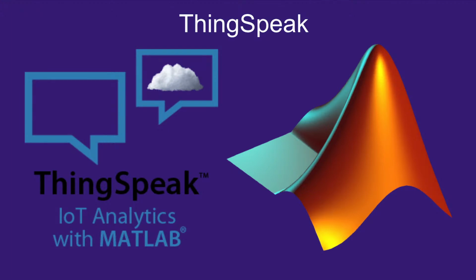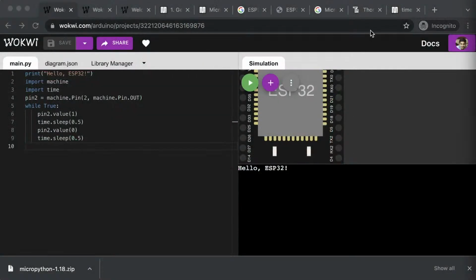ThingSpeak is an IoT analytics platform service that allows you to aggregate, visualize, and analyze live data streams in the cloud. It provides instant visualizations of data posted by your devices to ThingSpeak, and you even have the ability to execute MATLAB code in ThingSpeak so that you can perform online analysis and processing of the data as it comes in. ThingSpeak is often used for prototyping and proof of concept IoT systems that require analytics, just like what we are doing right now. So let's now jump to our Chrome window and set up ThingSpeak Cloud.